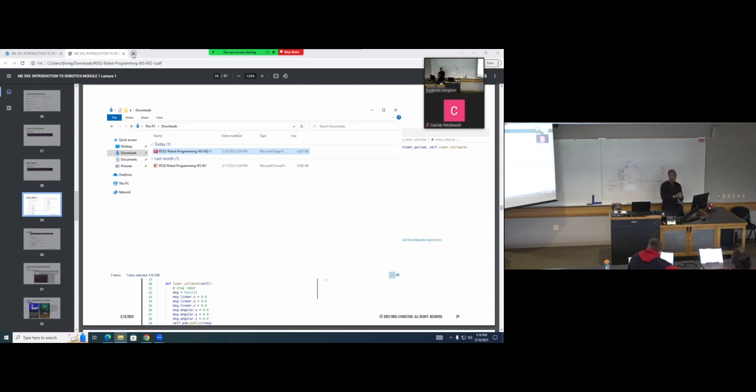So it's taking that velocity and you're tuning that PID to make that velocity respond like it should have. That's more of the hardware side of things. The software just takes that velocity and says, okay, move that, but the actual controller takes that velocity and converts it into PWM motor signals to give that velocity direction.